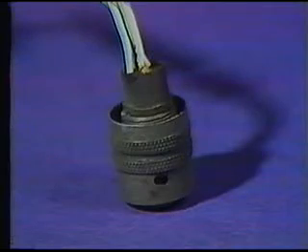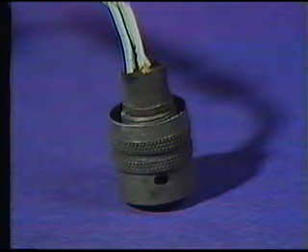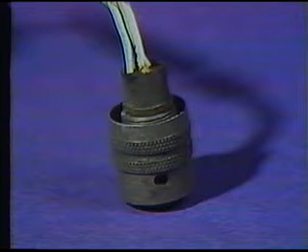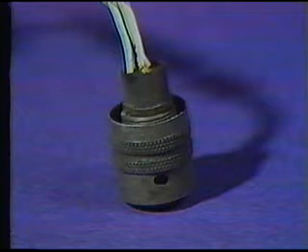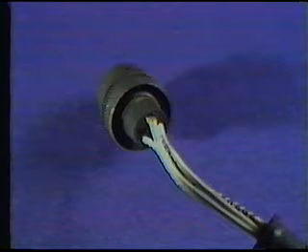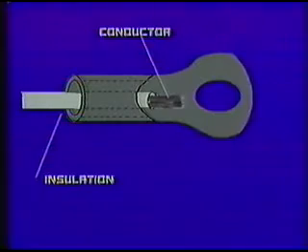Another nuisance area are repaired or improperly installed connectors, such as crimped pins and connectors, crimped terminals, and of course, crimped splices. These devices are manufactured in numerous sizes, both in the size and gauge wire it will accept, as well as the size of connecting stud or terminal post. There will be cases when abnormally small wires are crimped to larger terminals. The same applies to crimped pins or splices. This exaggerated example shows what we mean.